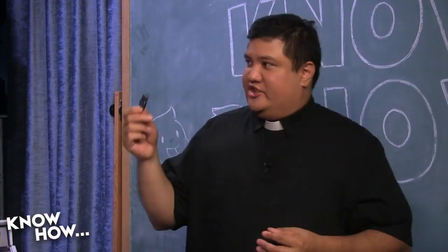This is an RTC, a real-time clock, and just like the name might suggest, it's an actual clock. There's a clock on here with a battery so that even if the Arduino shuts off, it's going to keep time. Nice. This clock will always run, and it's always going to run at a predictable rate, which means it's going to give me the actual time. That sounds perfect. I can program my Arduino to open the gate at 6 a.m. and close the gate at 6 p.m.